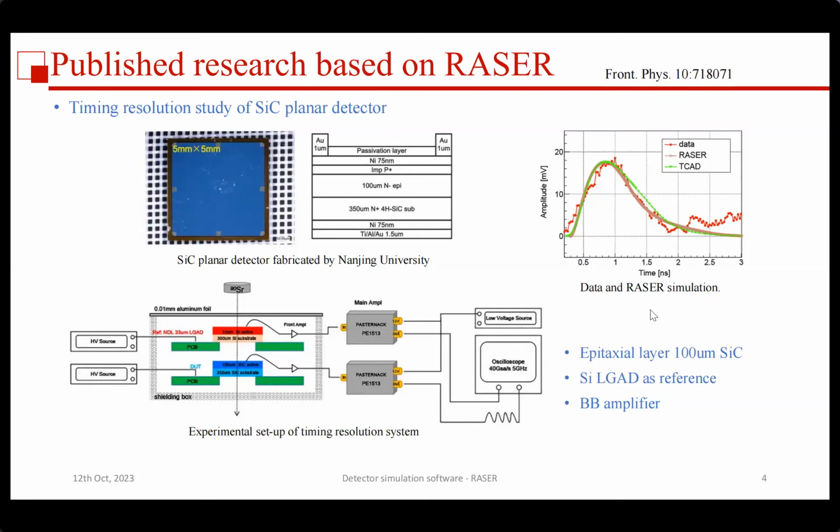You can see in this plot, the RASER simulation is close to the experimental data, and we also put the TCAD result here for comparison. The simulated timing resolution we get from RASER, 73 picoseconds, is rather close to what we have from the experiment, 94 picoseconds.